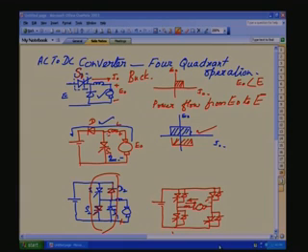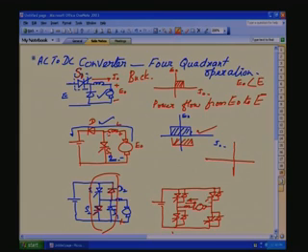If you go to the next page here, we want the load both positive and negative, so a positive waveform and a negative waveform. Okay. So, I put a sinusoidal voltage. Is it possible? With duty cycle control, I can have variable voltage. At very many instants, I can have different voltage, so that I can have a sinusoidal voltage. At the same time, I can have a sinusoidal current also. That means both positive and negative current is possible. Something like this is possible.